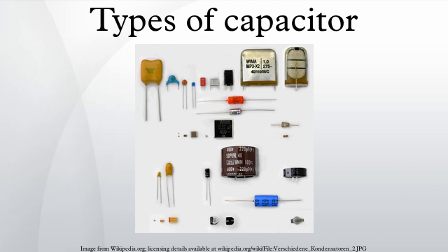Capacitors are available in geometrically increasing preferred values specified in IEC EN 60063. According to the number of values per decade, these were called the E3, E6, E12, E24 etc. series. The range of units used to specify capacitor values has expanded to include everything from pico, nano and microfarad to farad. Millifarad and kilofarad are uncommon.